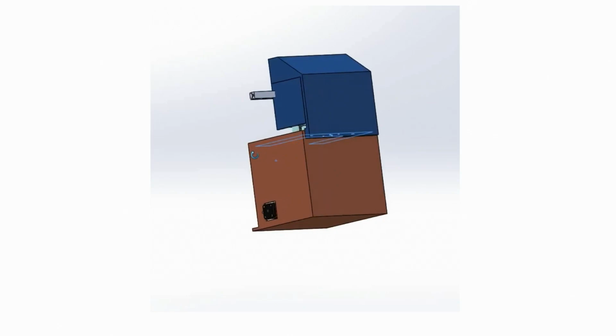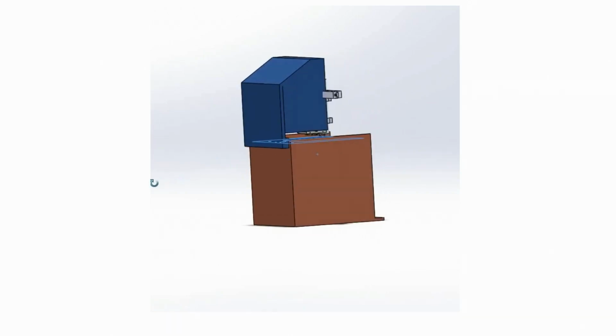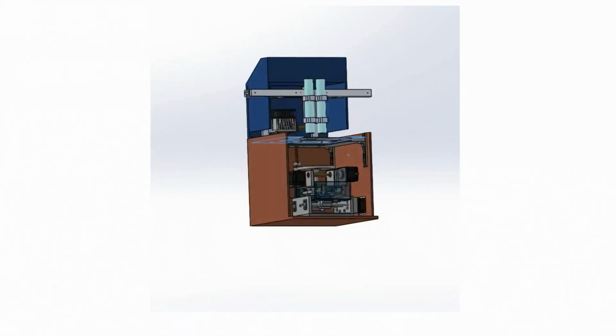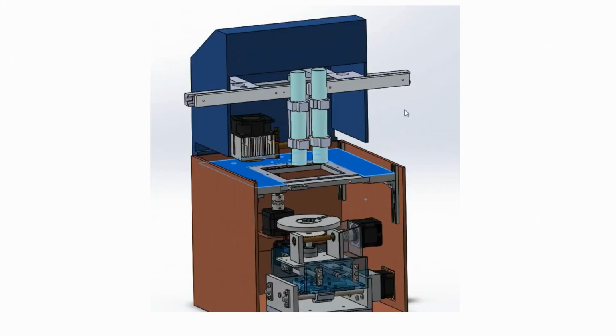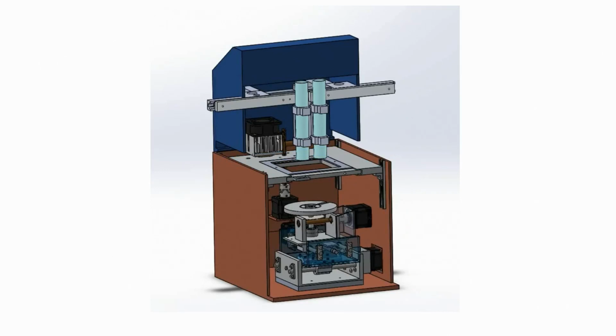This is just a simple box type mask aligner system. You can see its simplicity, and we want to see whether we can obtain the similar features which we can get through costly equipment, or close to similar features to costly equipment. We have not tried the minimum feature size in this case. However, we assume that we can get close to 5 microns very easily.